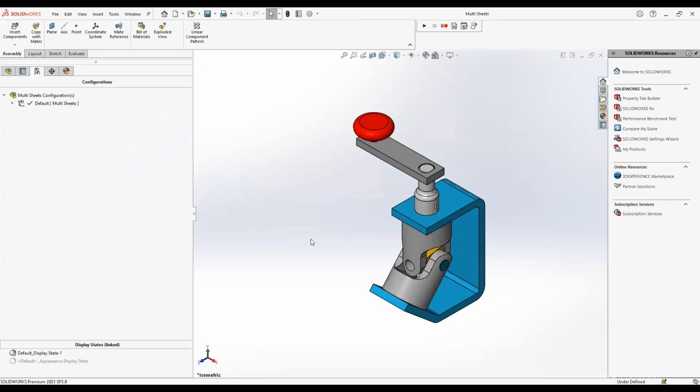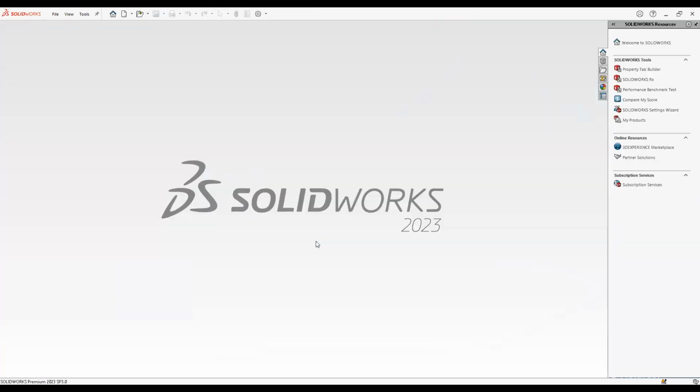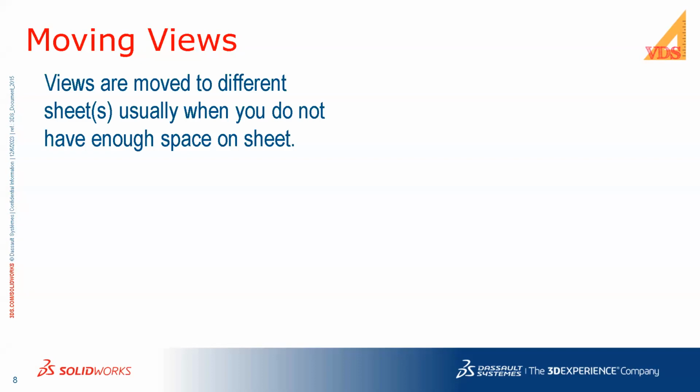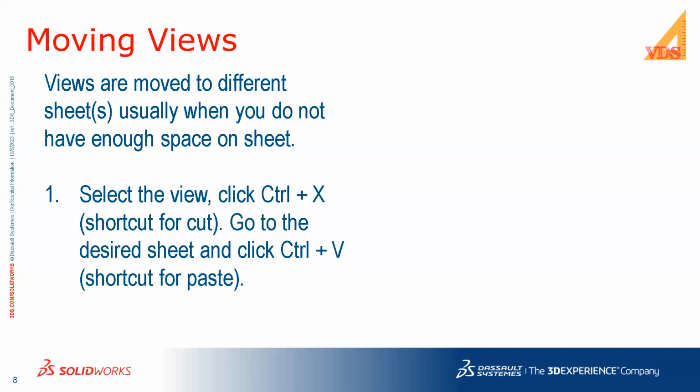I'll close this file. And we'll now move on to moving views. Like we were talking about in multi sheets, we can move the views from one sheet to another while keeping them linked, so that we can have our drawings look cleaner and easier to read. And why do we generally do that? Because we don't have space on the sheet.